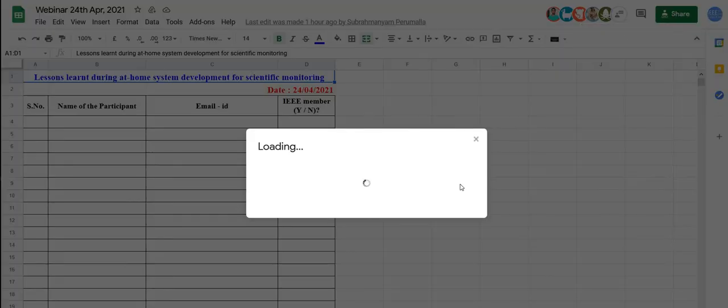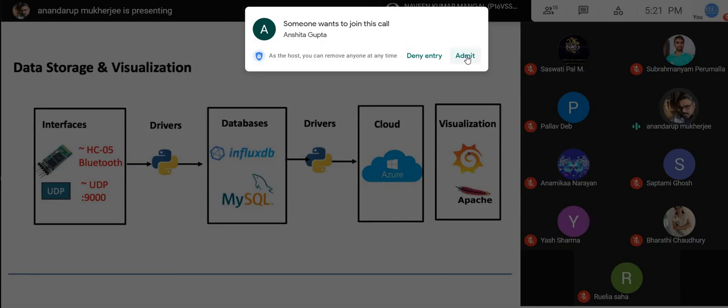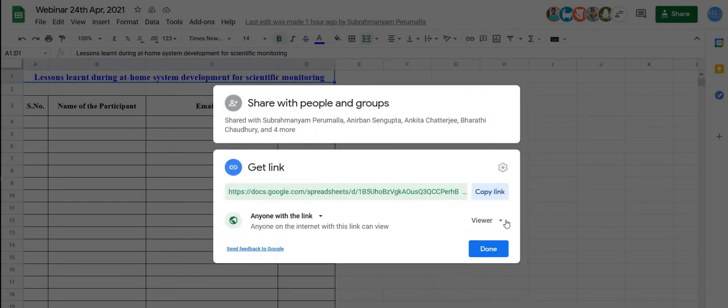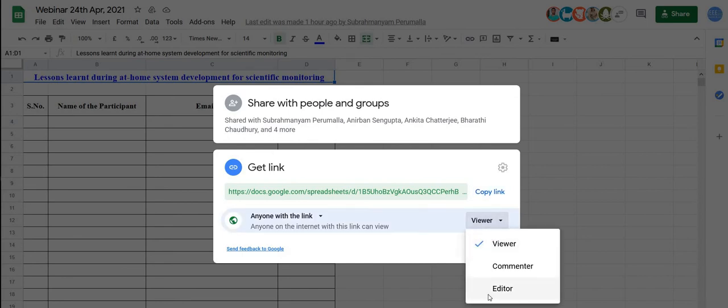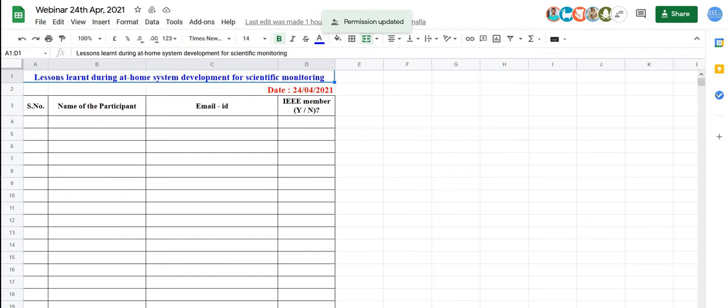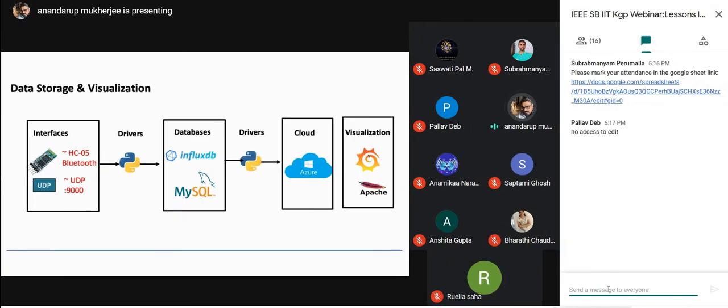However, sometimes it was seen that there are data drops, especially when the data sampling frequency is quite high. Like, for example, the vibration sensor tends to have a high data push rate, and most of the packets get dropped. So there was inconsistency. To make things more manageable, it is advised that some kind of an event-triggered server is used.